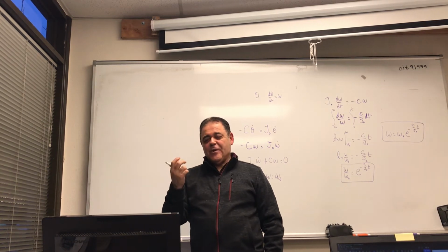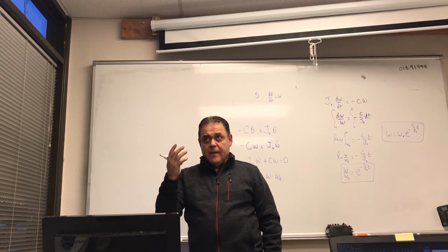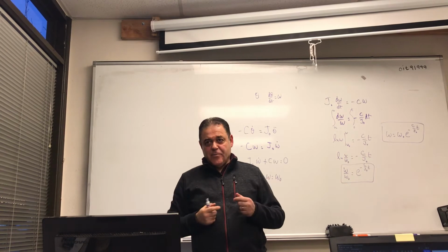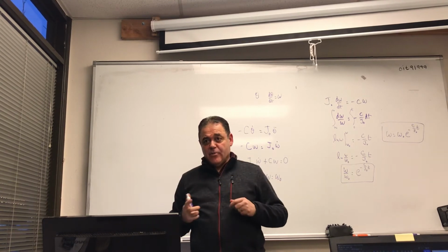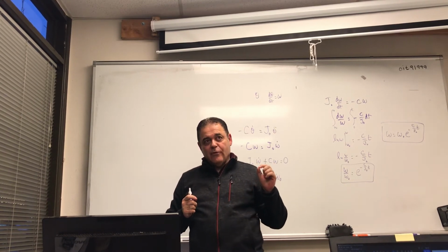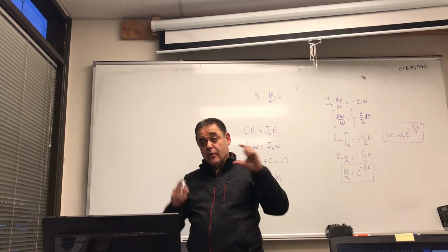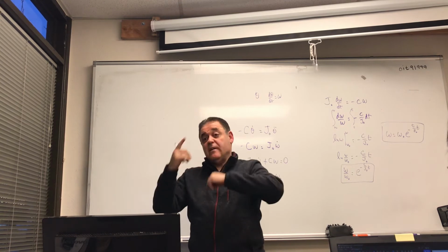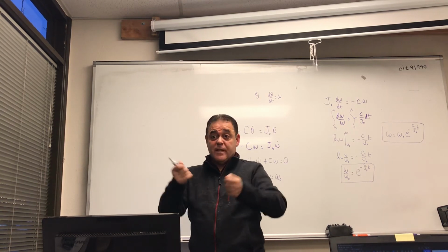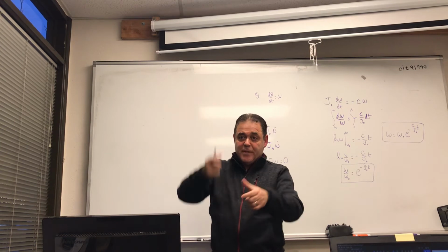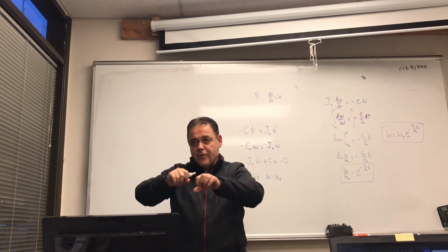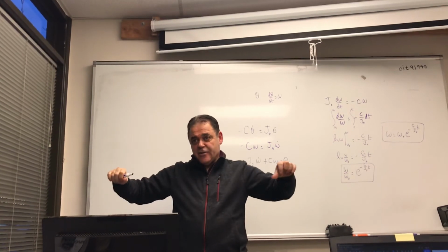Remember, when we're talking about linear systems, we have masses. The springs and the dampers are just peripherals, I guess we call them, that control how that mass is moving. But anytime we solve for x, we are really solving x for the mass that is moving. And its rotation is about whatever is rotating. Like if it were the disk, it's not the shaft of the disk, but it's really that disk itself. In this case, it's the motor, but not the shaft. The shaft is just a means of transmission.